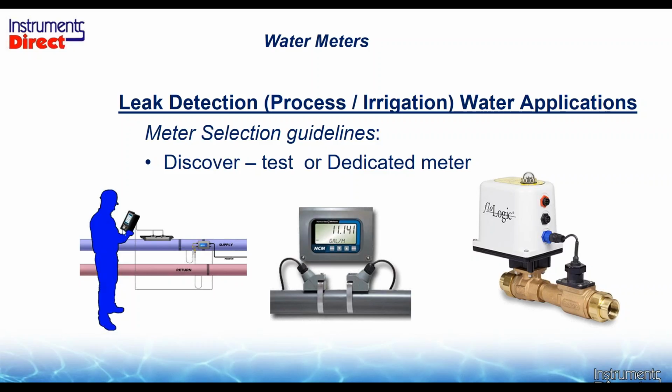And so you can do that as a portable basis. You can do that as a dedicated basis there. Or you can actually get technology that you plumb into lower line sizes that basically learns your application requirements. And then when those application requirements deviate, so I'm getting flow when I shouldn't get flow, this device basically says, uh-oh, we got a leak someplace, I'm going to turn it off automatically. So it's taking care of business by programming and not necessarily with you monitoring the situation there.